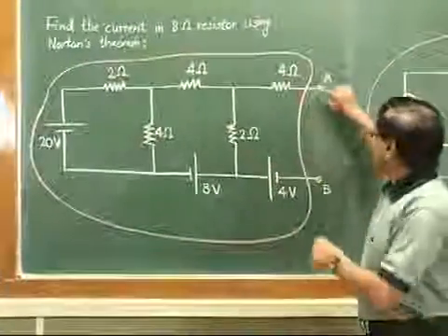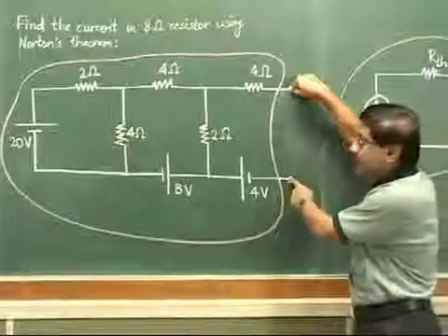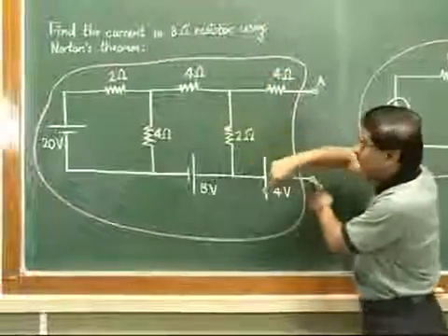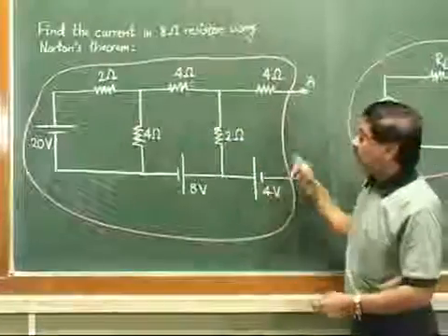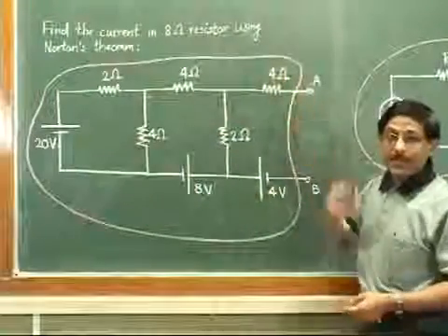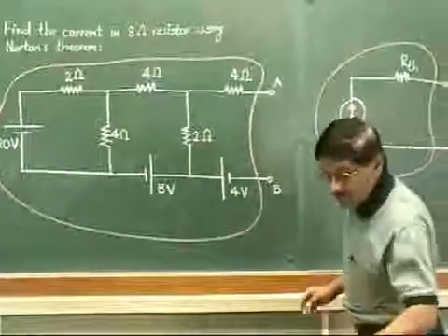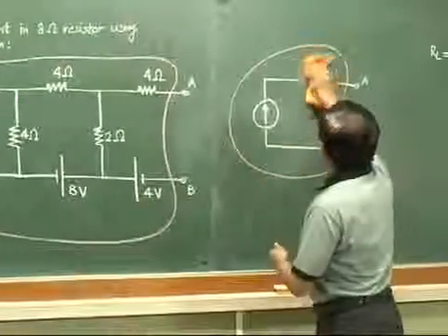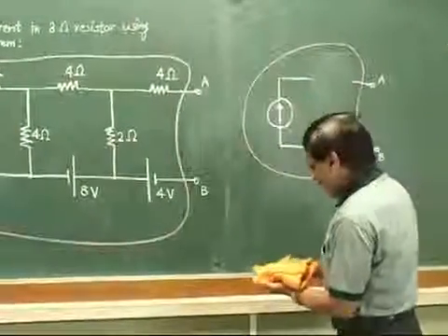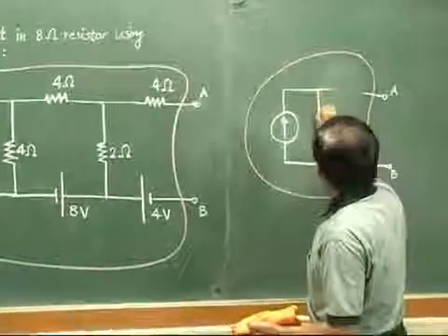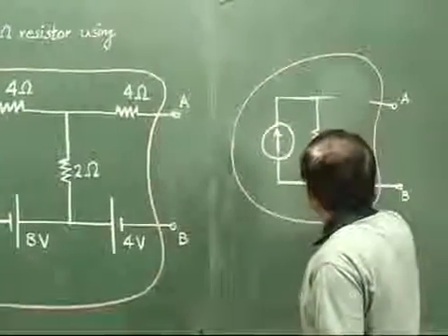So here we find some single value of equivalent resistance given by the entire passive network enclosed in this red enclosure, red line. And then we connect this resistance not in series like this, but we connect it here in parallel with the current source. So the things will be represented like this.